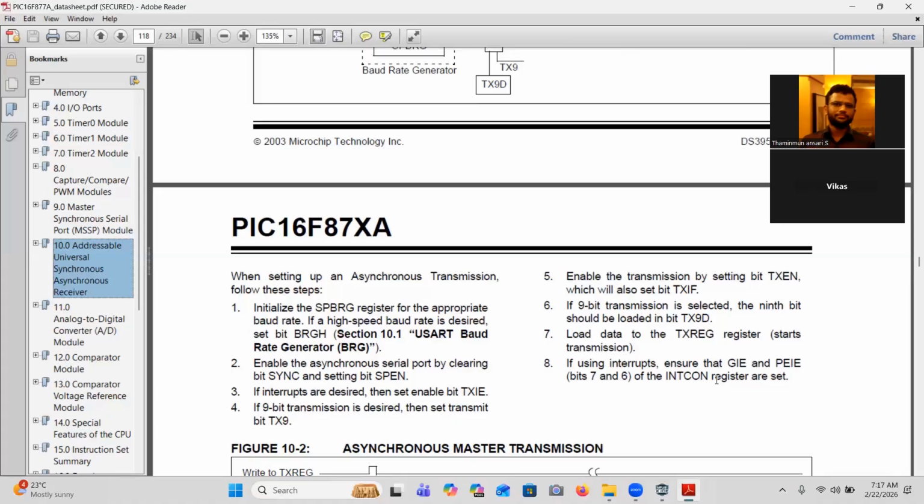All peripherals in the microcontroller have a head. That head is called the peripheral interrupt enable. Once it is enabled, only then can we enable the individual peripheral interrupts like timer interrupts, ADC interrupts, serial port interrupts. So they have the total control under the PIE, and the PIE has a master, the global interrupt enable. If you disable global interrupt enable, though you enable PIE, a particular peripheral's interrupt like a timer interrupt or ADC interrupt, whatever it is, will not work.